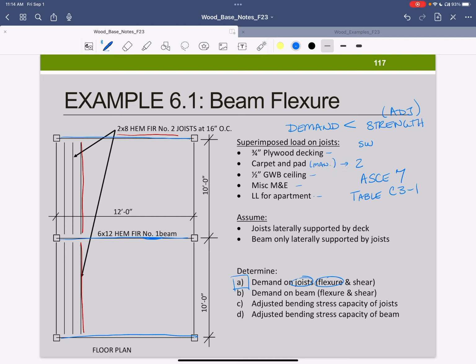We're going to use 2 pounds per square foot, which if you don't know what it is, that's a reasonable assumption for your first iteration. Once you know the actual final design values, then you go back and you make sure your self-weight's right, you make sure any other things you've assumed are at least conservative, and adjust accordingly. Okay, so this table is uploaded to the Canvas site. So you will want to go look into that to find these values. I will start in this problem and fill in these values, but that's where they're going to come from.